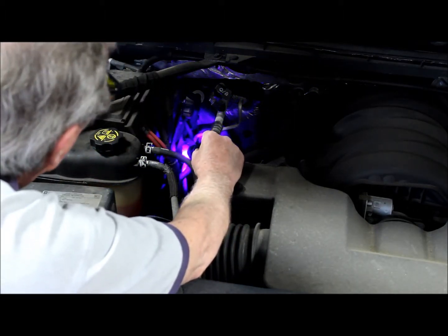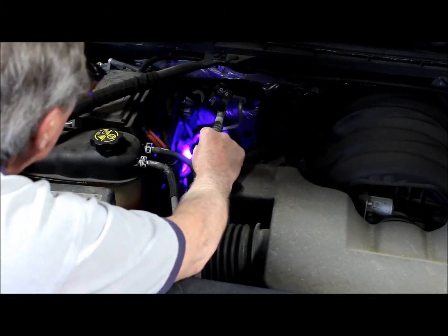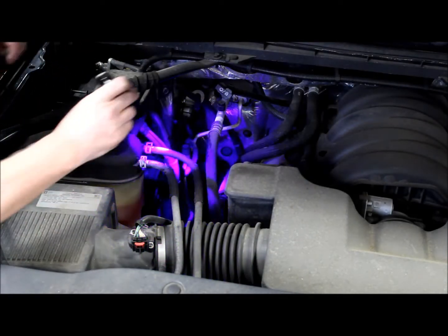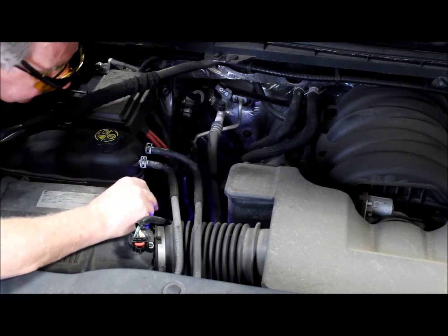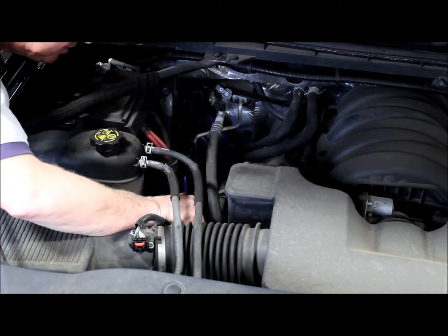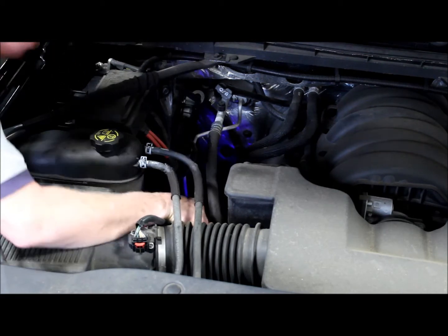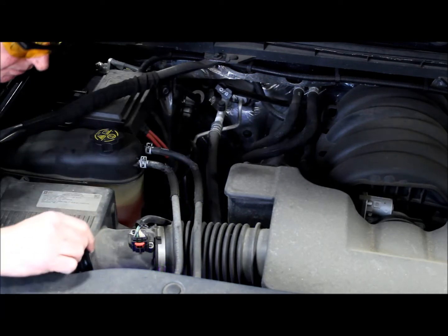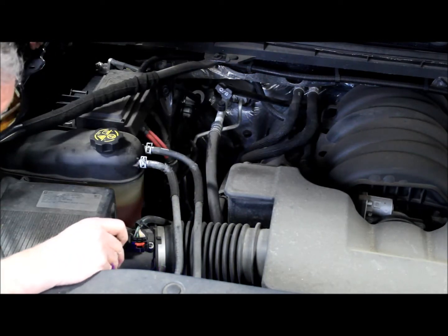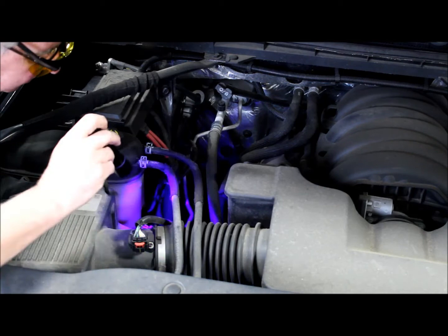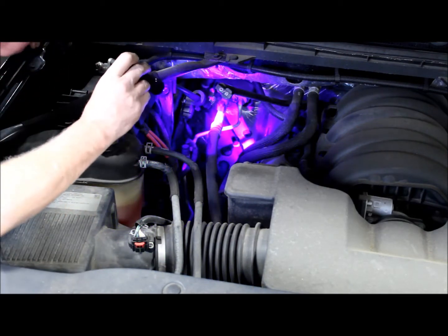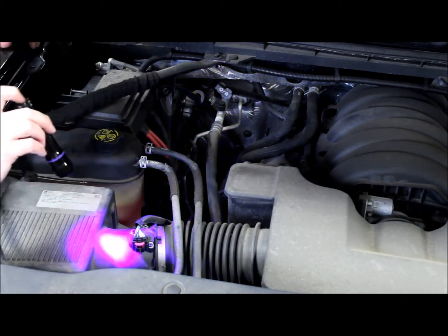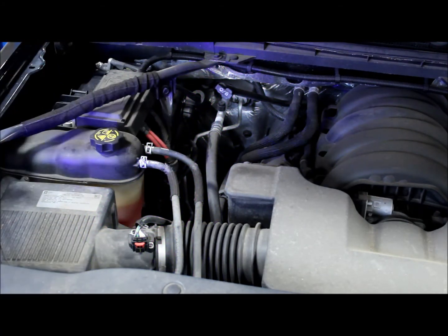It's lighting up a little bit, although not very much. And then I can check the rest of the lines going down towards the compressor that I couldn't see from the bottom, and going to the condenser. So far I've seen no evidence either with the visual inspection or with the ultraviolet that would identify to me any kind of a major leak that could cause this system to be completely empty.